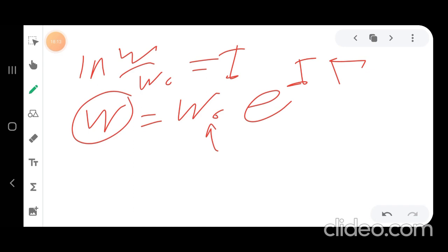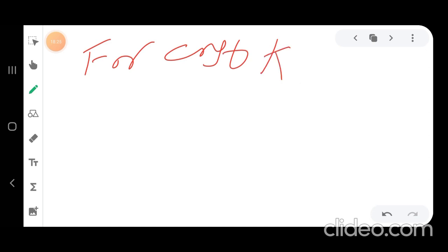Okay, that's it. And we have some special cases of this equation. The first special case is if you have a constant k distribution coefficient, and you know this distribution coefficient is y by x. If you have this constant, then you can use analytical integration. You will substitute y with kx.